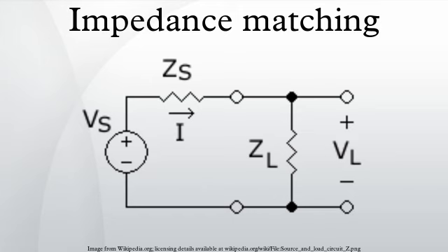Source end conditions. At the source end of the transmission line, there may be waves incident both from the source and from the line. A reflection coefficient for each direction may be computed, where Zs is the source impedance. The source of waves incident from the line are the reflections from the load end. If the source impedance matches the line, reflections from the load end will be absorbed at the source end.